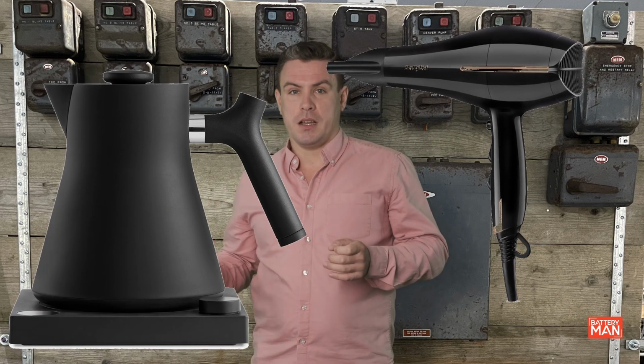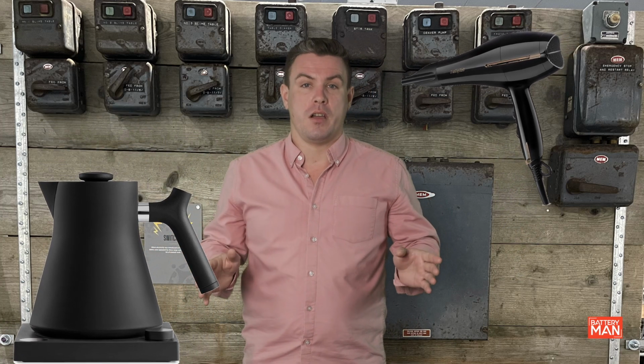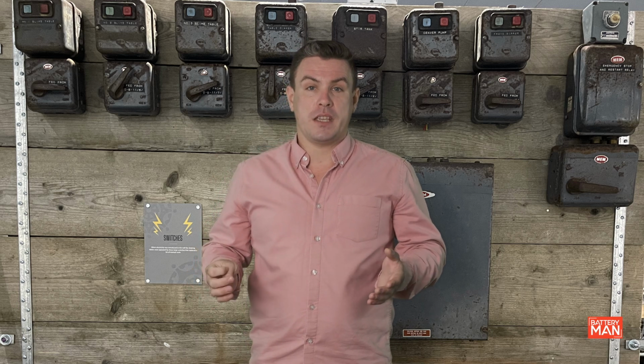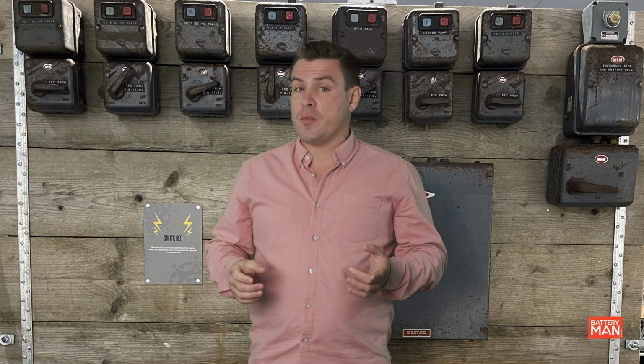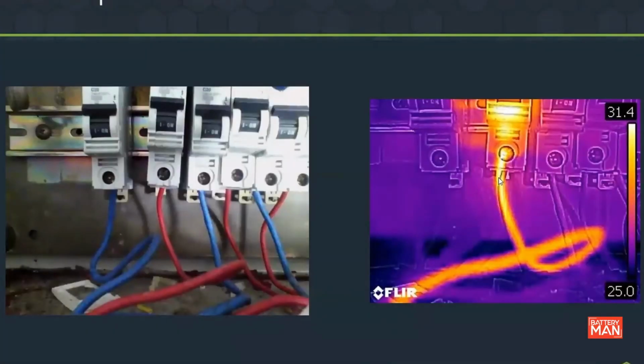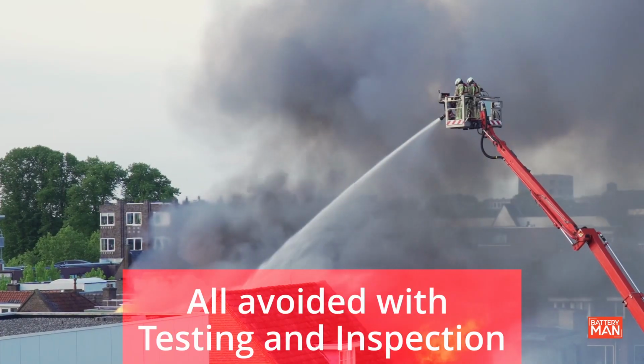You plug a couple of appliances into the sockets and they work. Great, you think. It works, I can go home. Well, you could easily have a break in that ring and have not found the issue. It's only when the broken circuit is overloaded. Remember, it wouldn't be overloaded if the circuit wasn't broken. So you get a call from the customer saying that the property's burned down. Oops.